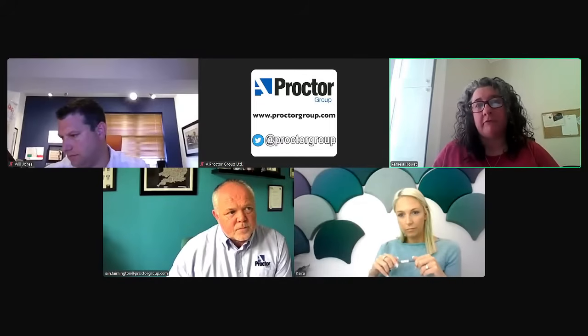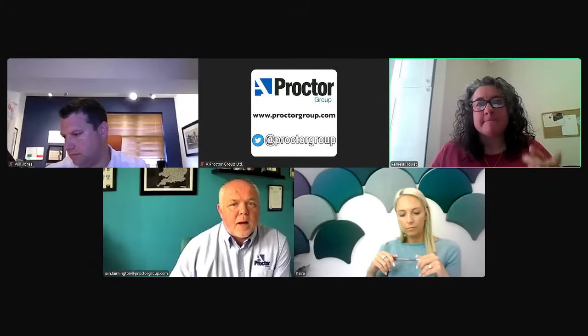It is right. 5250 does state that if the ventilation is there correctly and maintained, it should provide enough for protecting that roof. Is it a new roof? Sorry, I'm just thinking on my feet here. Is it a new roof? Could it be the drying out period? So we're watching a live Pam trying to work it through. I know, exactly.